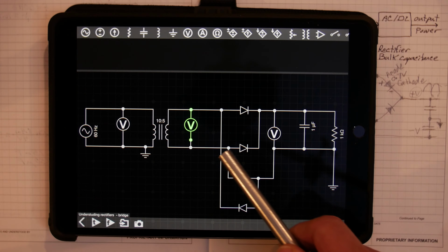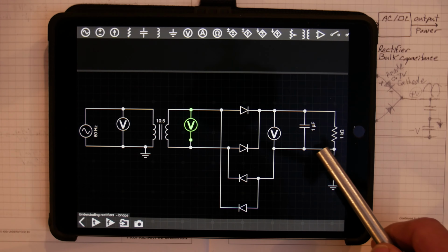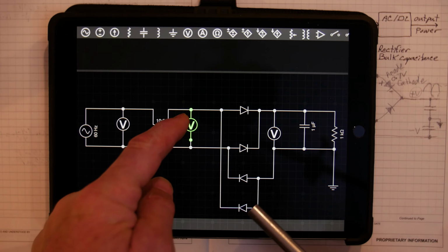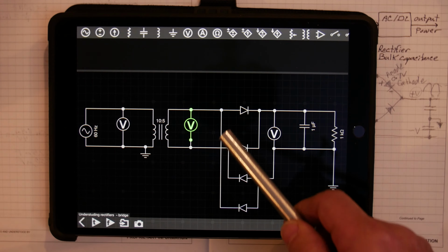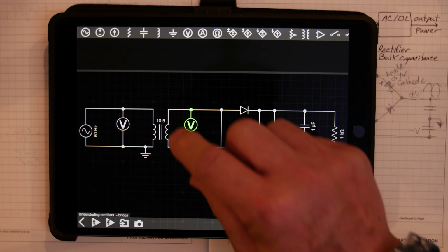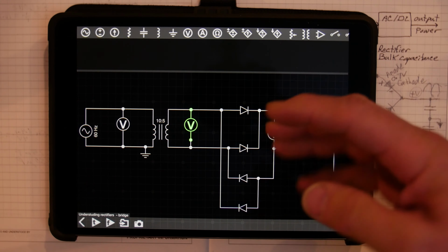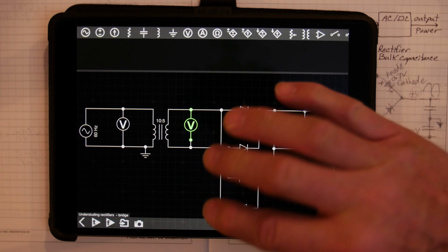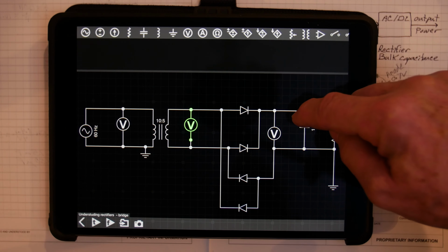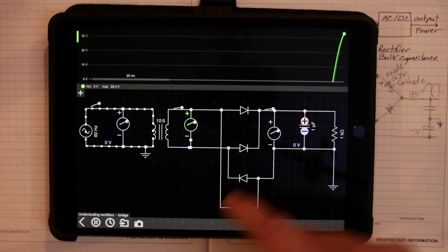Again, it comes through this diode, through here, down our resistor, around here, and it's got to find its way back up here, so it's this diode here. Comes to this diode and comes back there. So that's our circle. These diodes are just steering diodes. They just help when the waveform is rotating back and forth, they steer the waveform properly, so we always have plus up here and minus down here. Okay, let's watch that.